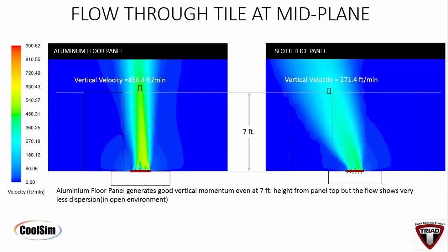And that's what we're seeing with these panels that are delivering. It's moving so fast, and that's what's causing some of this entrainment of the server fans themselves, forcing them to run at almost full speed. Some of the studies that are out there now show that if the air is presented correctly, the variable speed fan in the server itself will reduce its energy usage by a third. Wow, that's significant.